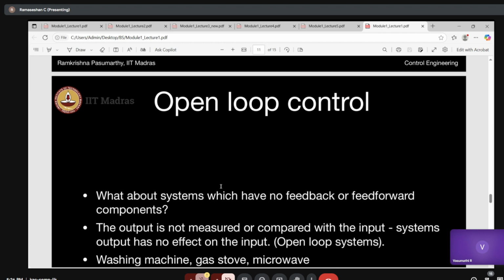Yeah. So the thing is, if K is very low, then you feed back not much. You are correcting only a little bit based on feedback, so the system will be slow to respond. Correct? That is obvious, right? Yes, sir. If K is very high, what do you think will happen? There are two problems. One problem is that even for a little error, since K is very high, the actuator signal has to be very high. That will spoil the actuator.